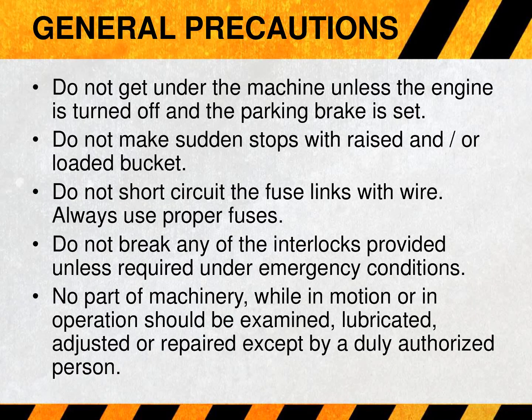Do not get under the machine unless the engine is turned off and the parking brake is set. Do not make sudden stops with raised and or loaded bucket. Do not short circuit the fuse links with wire. Always use proper fuses. Do not break any of the interlocks provided unless required under emergency conditions.